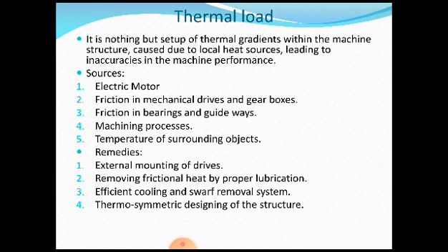Removing frictional heat by proper lubrication. This is one of the most important requirements as far as the performance of the CNC machine is concerned. This is possible by the continuous usage of coolant or lubricant, especially when a particular machining operation is being carried out. So there should be a continuous coolant pumping system made available in the CNC machine itself. Efficient cooling and swarf removal system.